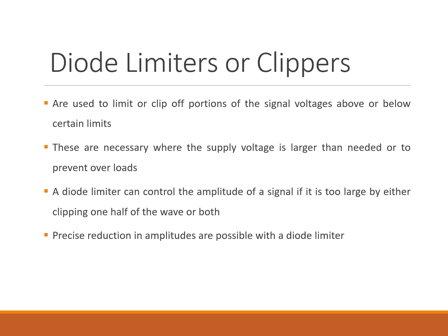A diode limiter is also called a clipper. It's used to cut off or limit parts of a signal that go above or below a set voltage. It's like placing a ceiling or a floor on a waveform, so it won't go past that. And why do we use one? Well, to protect components from overvoltage, so we don't want things getting damaged. We can also use them for signal conditioning in communication systems, and we can use them to create custom voltage levels in analog electronics.